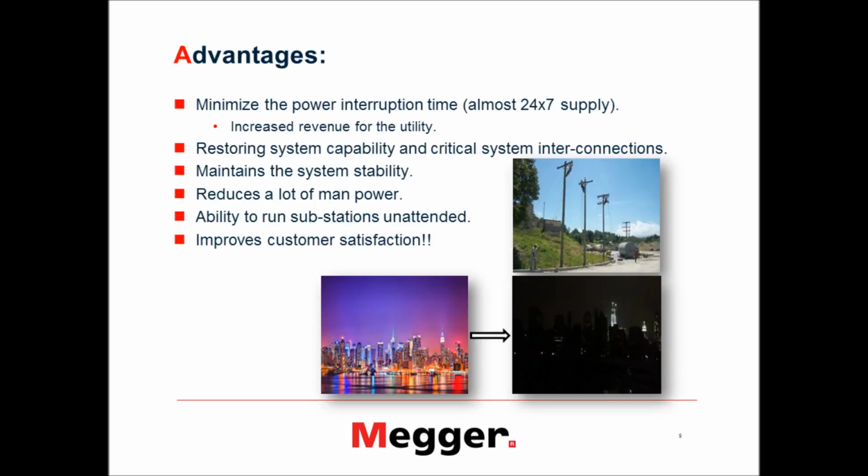So I'm going to talk about some of the advantages of having a reclosure in your system. First thing is, yes, it does minimize the power interruption time. So whenever there is a momentary fault, you restore the system, or you automatically close the circuit breakers, and the system becomes normal again. So you would minimize the power interruption time.